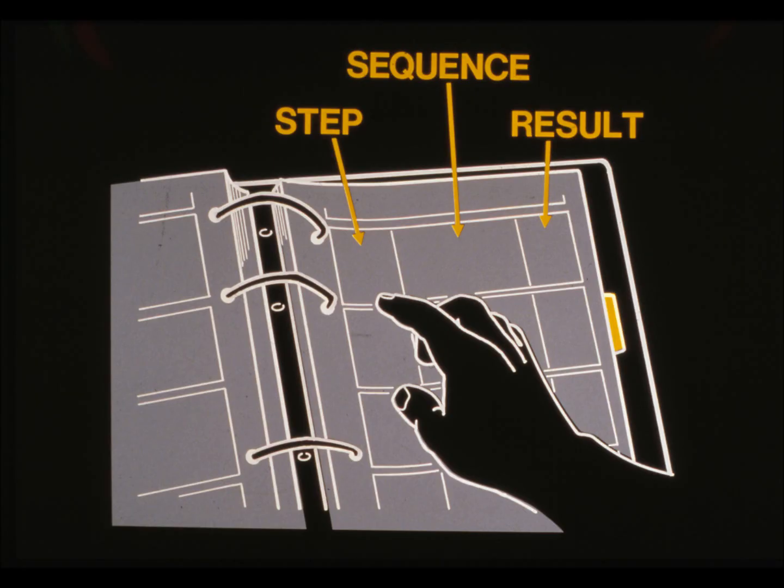The technical manual is designed to be an important tool in the hydraulic diagnostic procedure. It is essential to understand how the procedure is structured. Each step has a number. Each step has a sequence of conditions and tests to perform. In each step, you note the results of the tests. Depending on the results, you go on to another step.